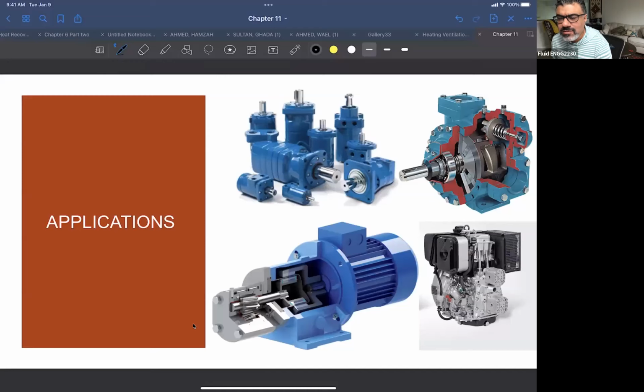Flow energy is the pressure times Q, right? Volume flow. So if it's a rate, it's going to be power. If you're talking about the pressure times the flow rate, that will be the power required to move the fluid. Which means that most of these devices are needed in order to provide this flow energy, basically providing flow rates at a certain pressure. As simple as that.